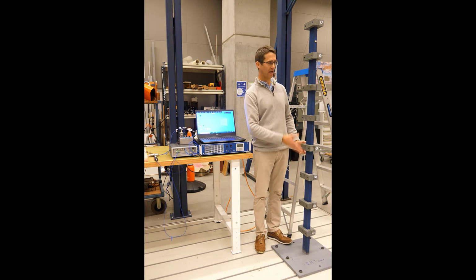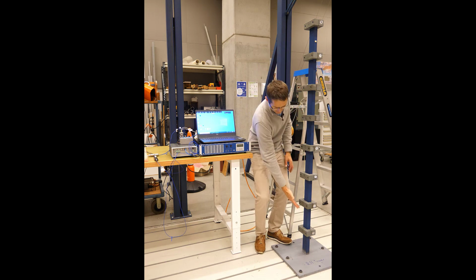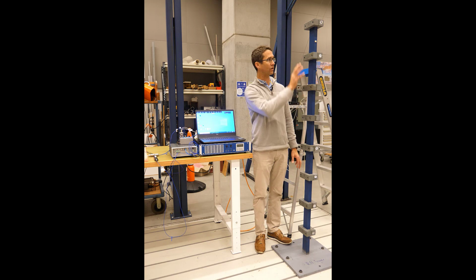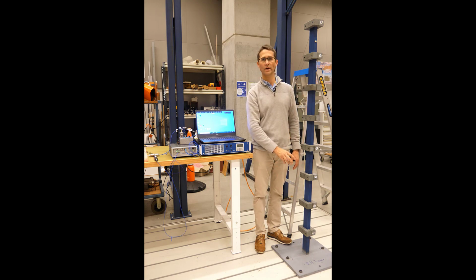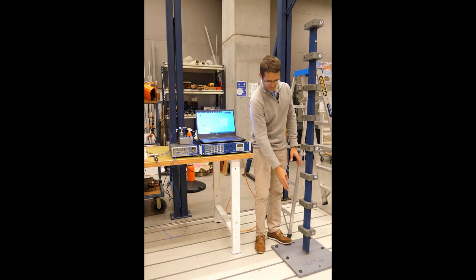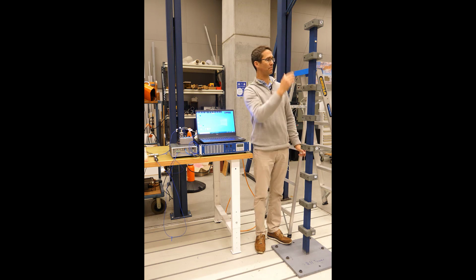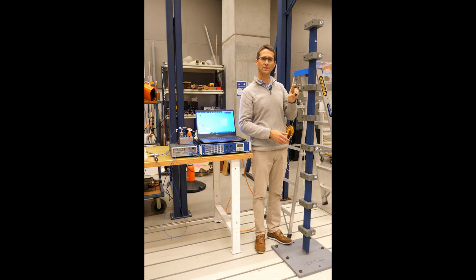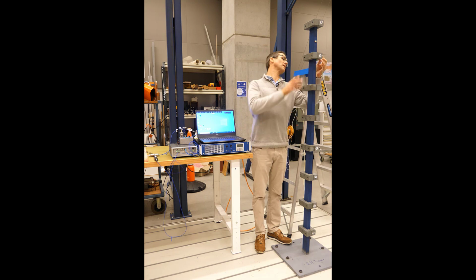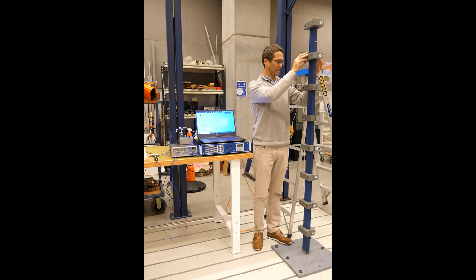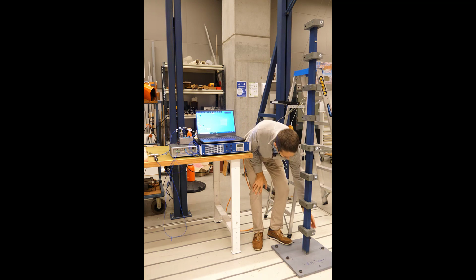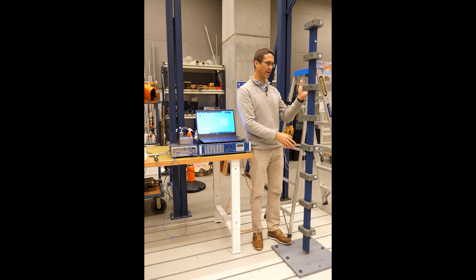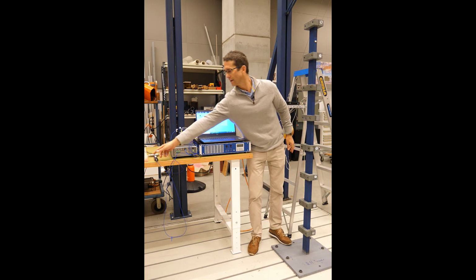We have an 8-story tower here to my left with 8 lumped masses evenly distributed along the length of this hollow rectangular cross-section beam, which is clamped at the base and free at the tip or the top. This tower has been instrumented with 2 MEMS variable capacitance DC response accelerometers, arbitrarily chosen to be mounted on level 7 and level 1. I have them on that side of the tower because I'm going to use my instrumented